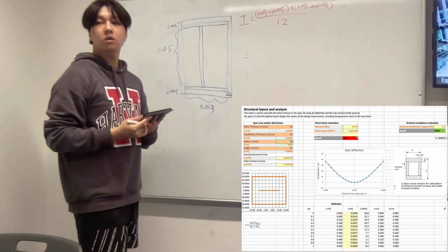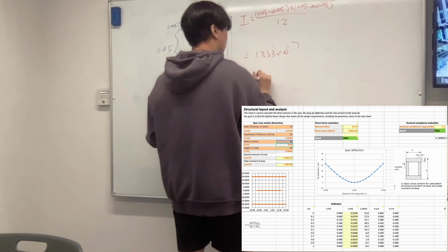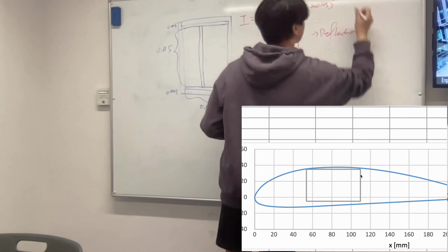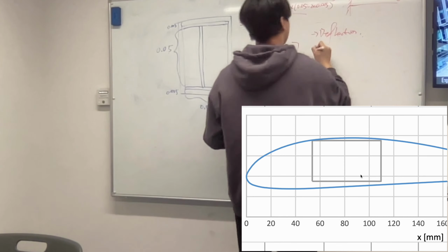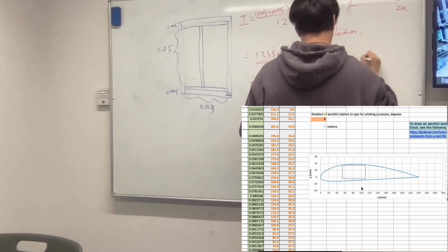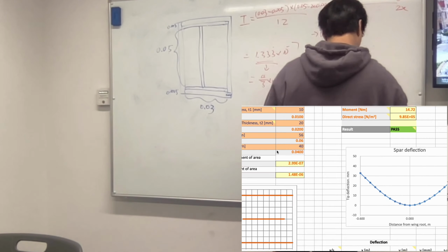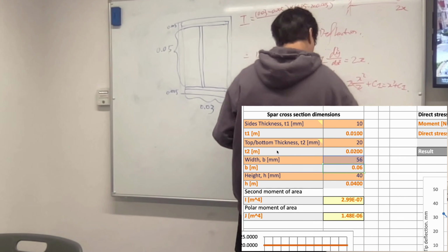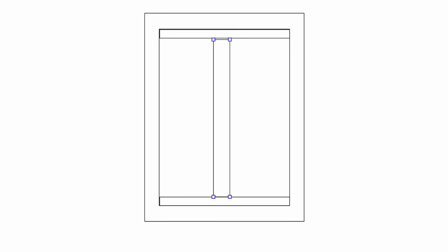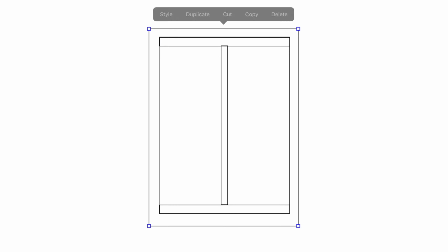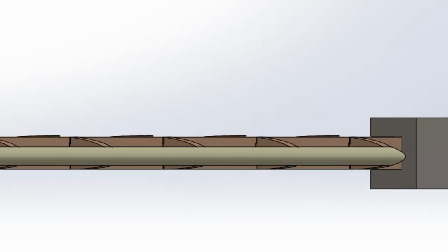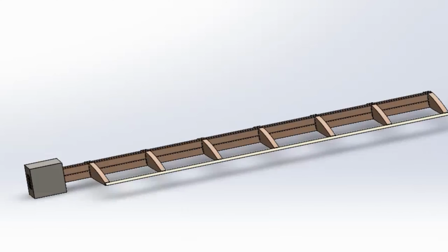Since both second moment of area and polar moment of area are based on the dimensions of the cross-section and the aspect ratio is given, we're basically making adjustments to the height and width of the cross-section, as well as the internal supporting structure. Calculations will give us a solid understanding of the dimensions we're going forward with. We then make an illustration via drawing as a clarification while building. A CAD model is also built in SolidWorks to show how the real wing will look like in 3D.